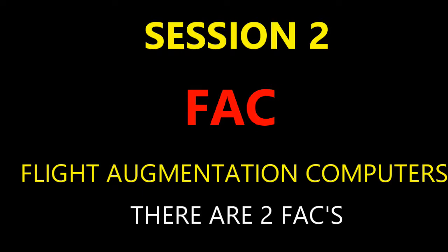Okay. You also have a power loop. It's just the feedback in the power loop that's given by the transducer for the command side, and then you have another one for the monitor side. So it's just in order to operate that. The monitoring: you do have monitoring at power up, so just making sure everything's good. So it's going through its safety tests, and then of course you have your ELAC, your FMGC, and your ADIRS. Those inputs are always being monitored, constantly being monitored.